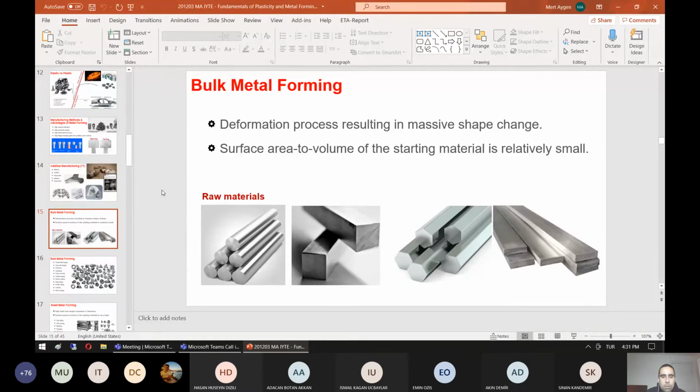It depends on the type of the process. If you are talking about the powder bed, yes, there will be some limitations regarding the laser power and the build space. But there are now new technologies like binder jetting, and that technology is quite suitable for large batch sizes of small parts. There, you basically don't melt anything. You just compact them with a binder material and then sinter them afterwards. So it's a very rapid printing process, and smaller parts will be cheaper, or the cost per part will be lower. But when we talk about big parts, of course, 400 or 500 millimeters in height, half a meter, they will still be a little bit more costly compared to the small ones.